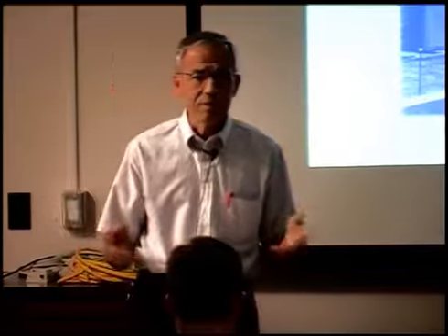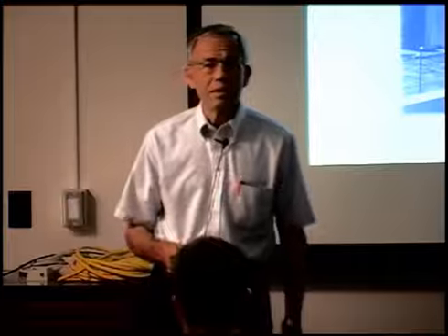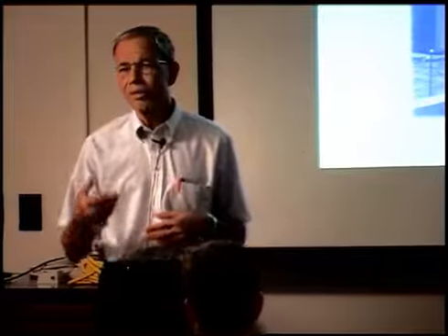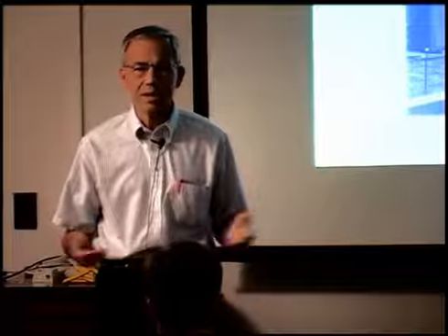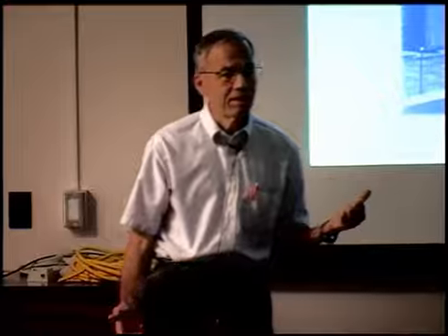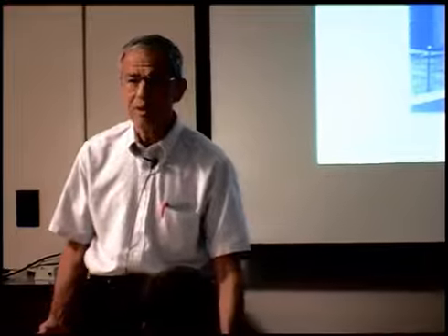One of the questions that we've tossed around among ourselves is, should we have some sort of a limit? If your friction capacity is less than a quarter of the total, you just forget about it and only go to the rock. We haven't made any kind of decision on that. The example shows the actual use of the friction plus the end bearing. So, rock will be covered in the Bridge Design Manual. It's also in your volume 4 in that track 1, example 5.